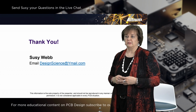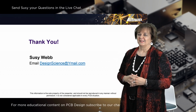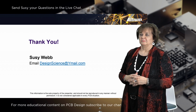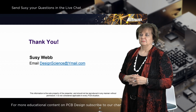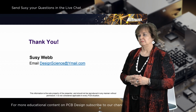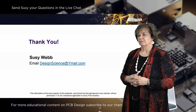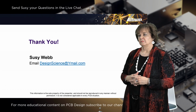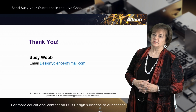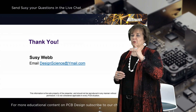There's one last, it's not really a question, it's more like him wondering. MR is asking, so he had some crosstalk at the beginning of his career, and he's wondering if trying to dampen the rise and fall time by applying a passive component, for example a capacitor, can help. I would put a termination resistor in series with it, rather than to limit the voltage of that signal.